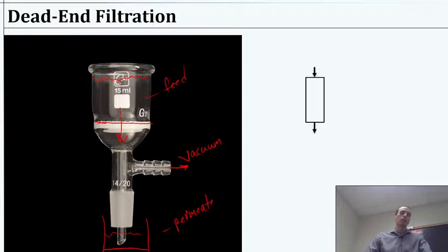And when we think about the different membranes that we might want to use, we could see that if we need this nanofiltration, we probably have to pressurize the feed with pumping pressure into it rather than trying to pull it out and use the atmospheric pressure. So we would have some consideration there. So I'll just write a little note.